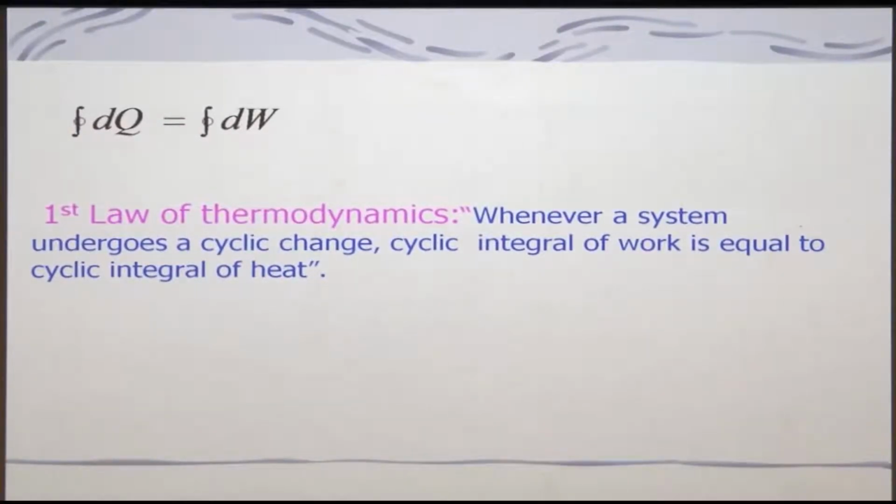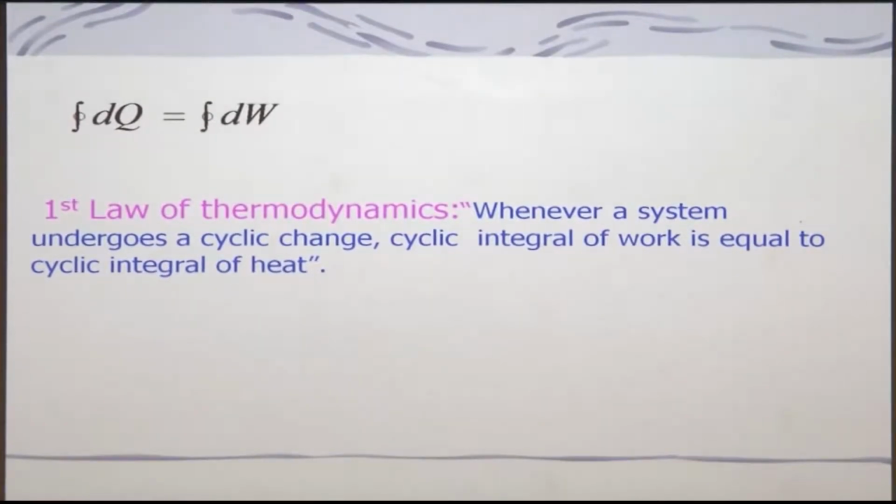Are you people aware about this? What you know as the first law of thermodynamics proposed by this thing is different than this, okay. But how it can be utilized, this first law of thermodynamics, we will see later on. So, this is the equation and this is the first law of thermodynamics, that the cycle integral of heat is equal to the cycle integral of the work. Keep in mind, this expression is valid for SI units, otherwise J should come into the picture. In SI units J is equal to 1, but in FPS units it will be different.